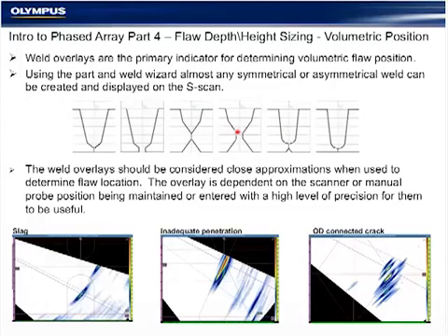The weld overlays are close approximations for typical scanners that don't have a band. The sector scan allows the scanner to drift a few millimeters in and out, so don't make a weld bevel precision measurement. It's just a general guideline for where the weld is at. The closer you can keep your scanner on target, the more useful the weld overlay is going to be.